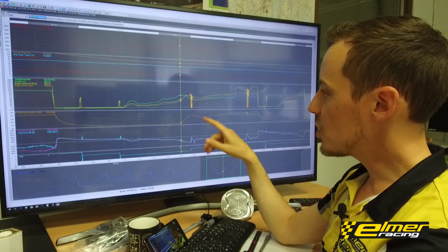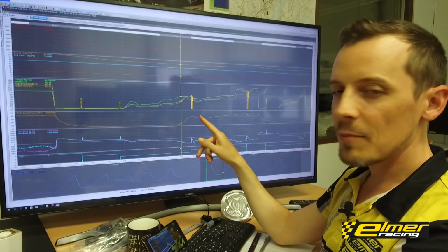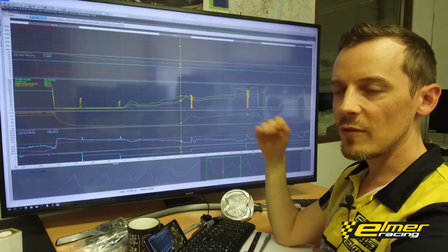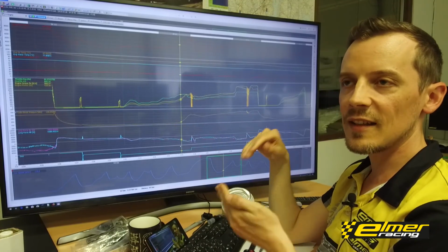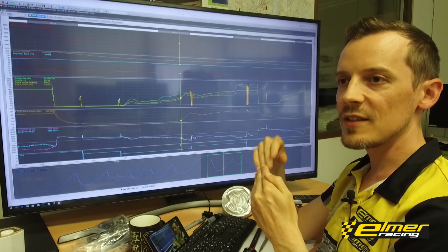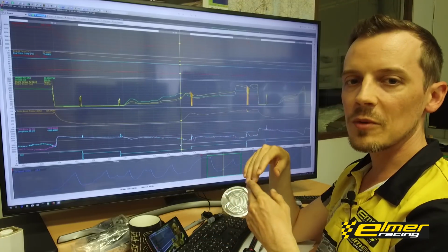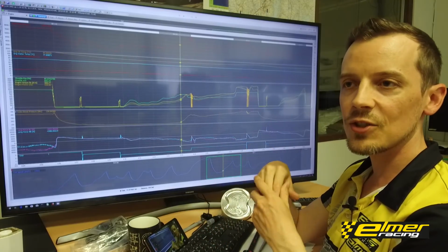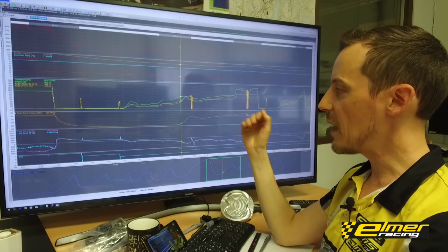And so the biggest question mark was coming out of turn 2 at a reasonably low engine RPM, will we have enough power there, normally aspirated, to be able to have enough power out of the corner, or will we need to start dialing in anti-lag? This will create more testing time and setup time and potential heat issues with exhaust manifolds, and we might need to use more expensive components for the exhaust manifold, which might take longer also to manufacture. So these are all considerations on looking at the anti-lag aspect.